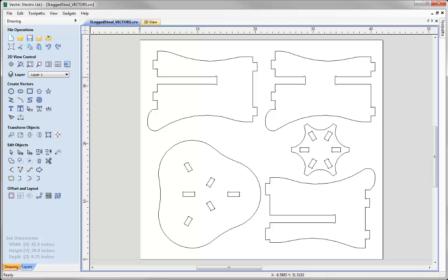In this tutorial we are going to import vectors from CAD drawing software which come in the file format of DXF. We'll look at the properties that get imported and some of the problems that you may encounter along the way. We also look at machining mortise and tenon style joints on CNC machines and how to overcome fitting issues with dog bone fillets.